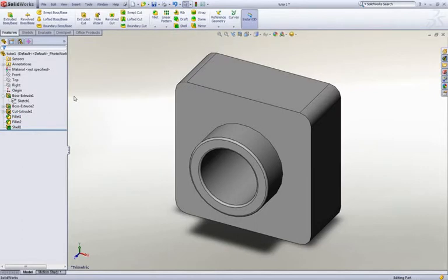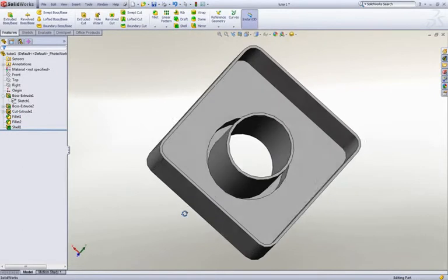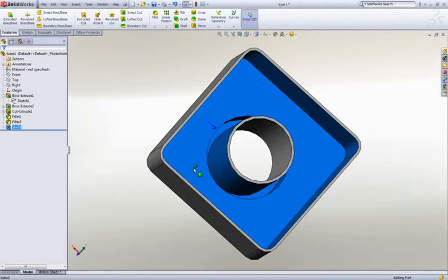Now the fillets on the front face must be recreated. This must be done before the Shell 1 feature, or else the inner edges will not include the fillets. In the Feature Manager design tree, hover over the blue rollback bar below the Shell 1 feature until the cursor changes to a hand. Then drag the rollback bar above the Shell 1.